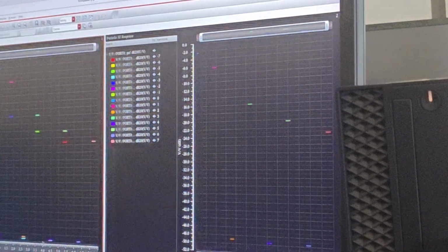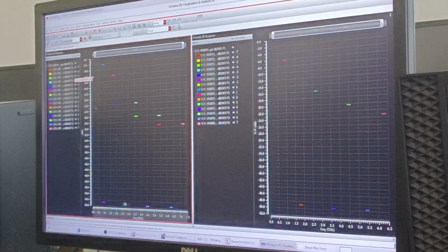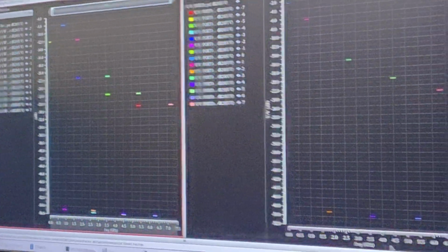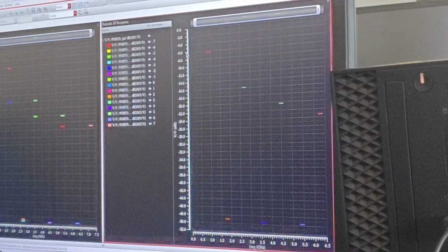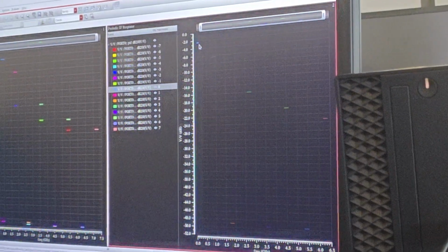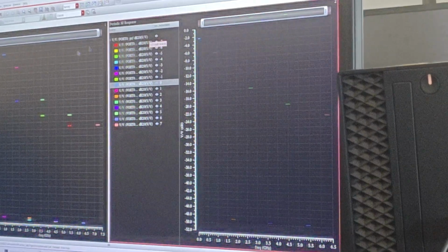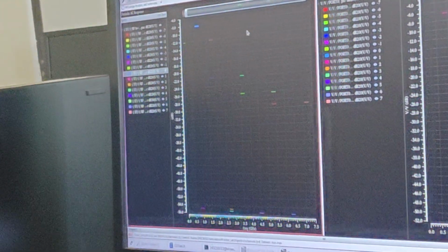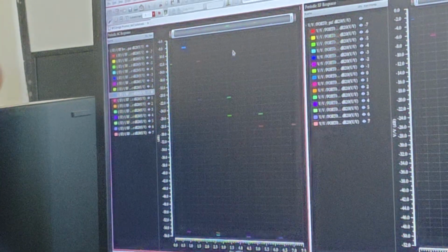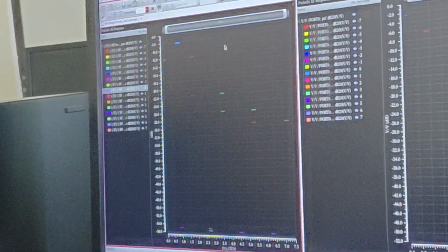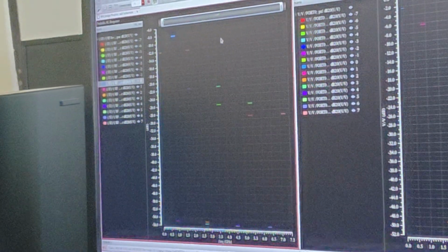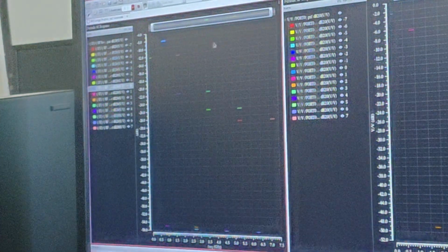This is with respect to the output scale. This is with respect to the input scale. PAC gave it with respect to the input scale, and this gave it with respect to the output scale. But if you see this conversion gain, you get minus 2.39 dB, and here you are getting minus 8.244 dB. Why is it coming out different?